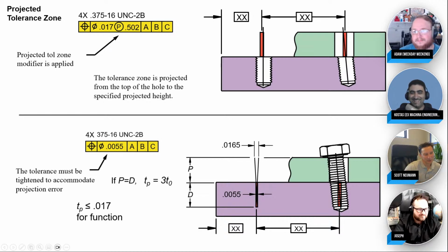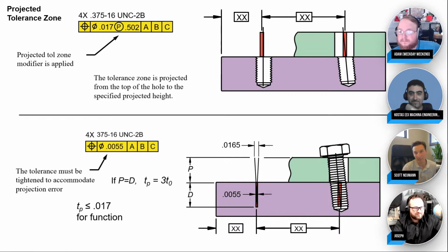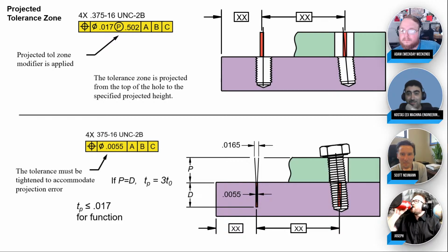The thing is, that's just going to cause interference. And really what happens is you put the torque wrench to that thing, it's going in, right? So you're going to end up cross-threading stuff. Cross-threading, shifting the top plate, and then another part doesn't fit, and then another part doesn't fit, and you're chasing. You think the problem is with the other part that doesn't fit, where this is where you made the error. It's so much simpler to just think of it and specify it properly.